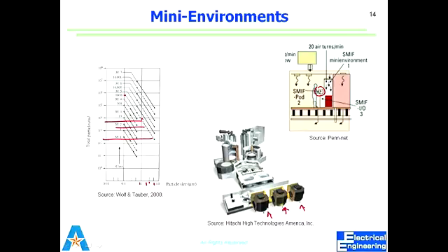We maintain positive pressure inside the clean room. What does that mean? More pressure than the environment. So inside is pressurized. Why do we pressurize the clean room? So that dust from the outside doesn't blow in, outside air doesn't come in. So even if there is an opening somewhere, air is always moving from in to out, not out to in, right? It may feel strange to some people if they are sensitive to pressure, but you get used to it.